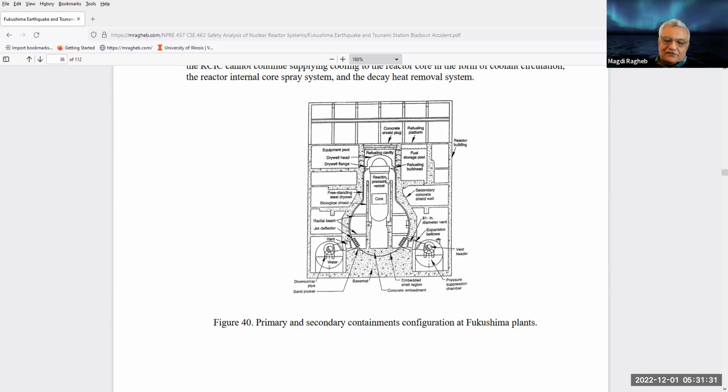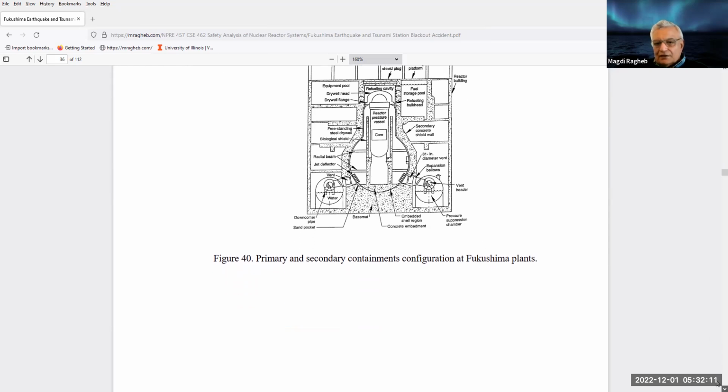If it were up, as I suggested, then you can have natural circulation to cool the core rather than having to run pumps and quench the steam that would be produced in an accident in the pressure suppression pool. But if this area is filled with water, and you end up in a situation where the core melts, it will find ways of leaking through the control rod inlets. And if there is water there, we studied the steam explosions before, you can have a monumental interaction between the water and the corium material, the molten fuel, in the area under the core.